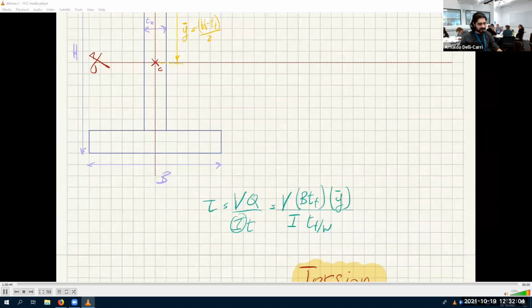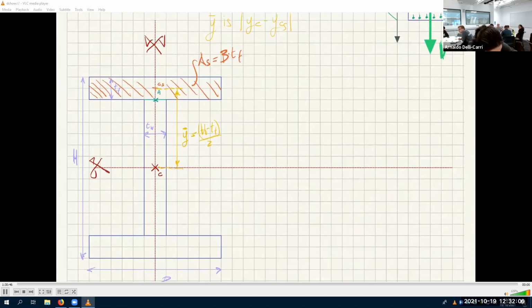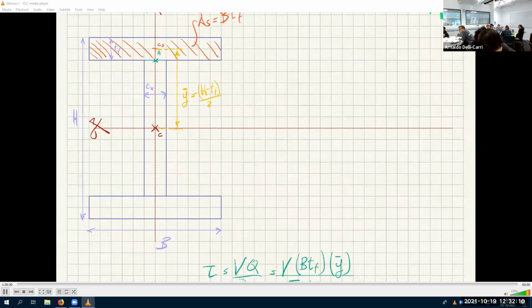the other side. Because at A, what you have at A is this thing here. So if I draw the shear stress diagram, this is tau. Tau starts at 0 here, and it must end at 0 here. How do I know? Well, I'll show you now.